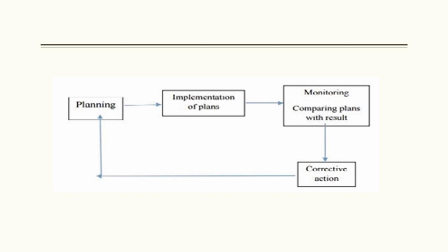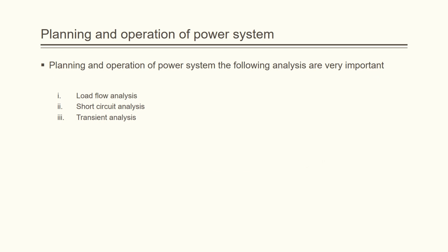Various studies in power system are load flow studies, short circuit study, electromagnetic transient analysis, stability analysis, economic dispatch, load frequency control, and harmonic analysis. So a few of the analyses have been noted. The load flow analysis, short circuit and transient analysis play a major role in system study.